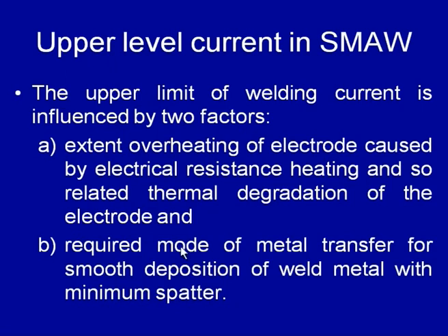One is the extent of overheating of the electrode that can lead to the thermal degradation of the electrode coating, and the second factor is the mode of metal transfer that is required for smooth deposition of the molten metal with the minimum spatter.